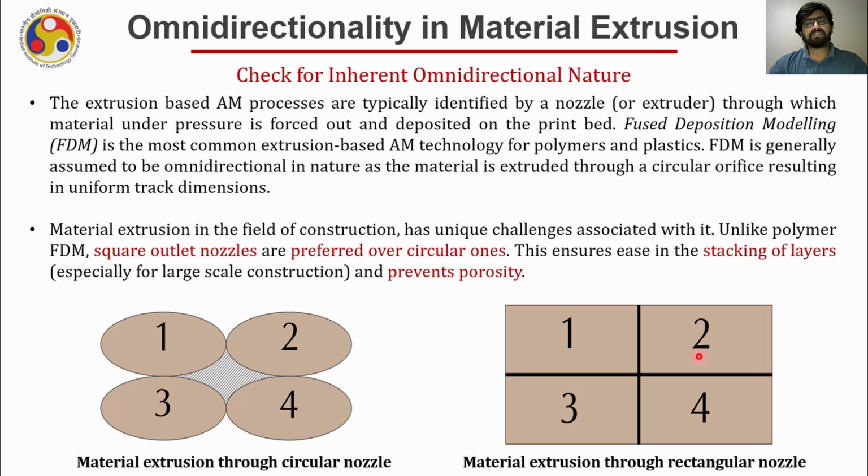So the extrusion based additive manufacturing processes are typically identified by a nozzle through which the material, under pressure, is forced out and deposited on the print bed. Fused deposition modeling is one of the most commonly used extrusion based additive manufacturing technologies for polymers and plastics. FDM is generally assumed to be omnidirectional in nature, as the material is extruded through a circular orifice, resulting in